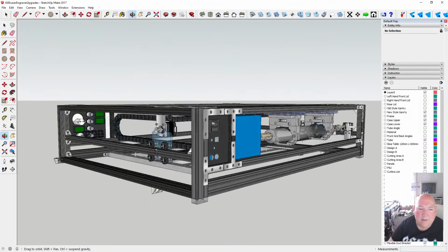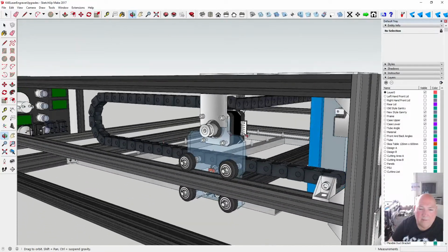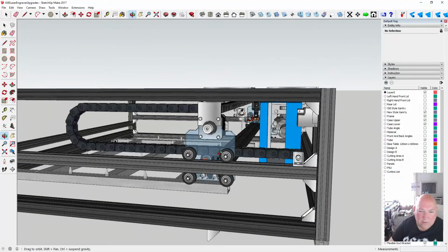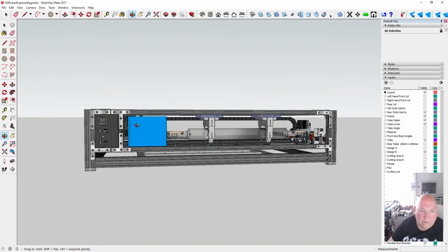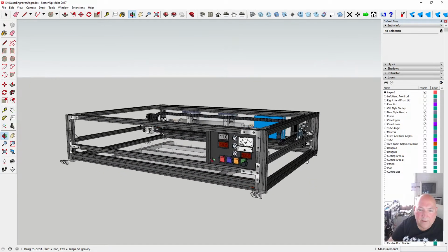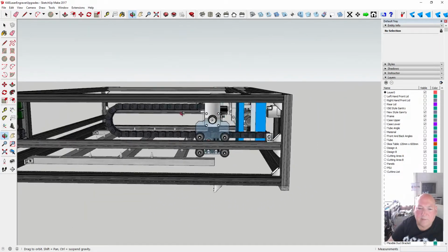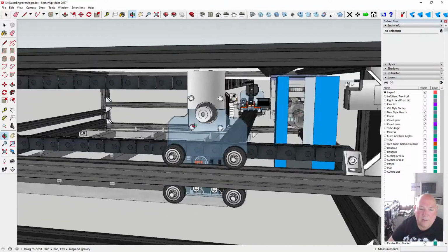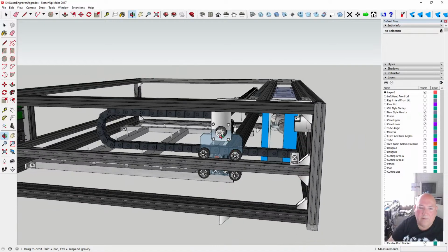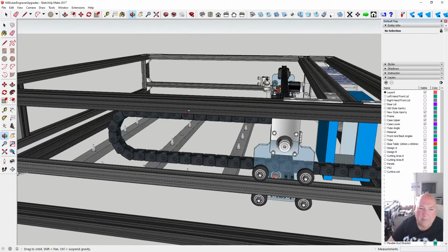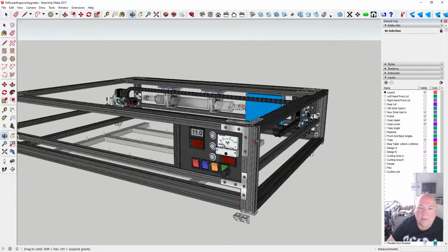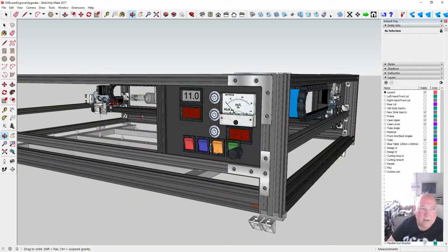Anyway, so we got close now. I've managed to wire these up so they go in the same direction, both ends. I've wired the limits up, I've wired the power up, and I've wired the control panel up. So now, what I was going to do today is put the belts and pulleys on, clamp them in, because then when I do the test maneuver on the software, we can see it moving around, which we haven't seen yet. I think that'll be good. And once we've got it moving around, then we'll arrange where all this has got to go.